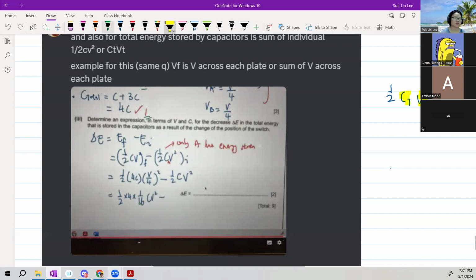And also this one is a bit sus, because this total voltage, if the potential is different for whatever reason, then you cannot take the total voltage already. Because let's say this is 3 volt and this is 0 volt, the voltage is not the same. What is the total voltage? Don't know. So this one kind of only works if your capacitor is like this, where your V_T is the whole thing. You can try it out with different equations.